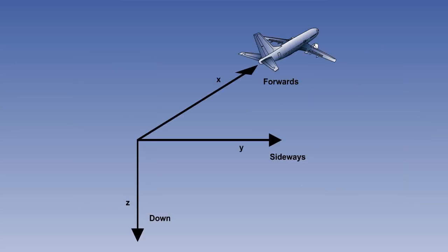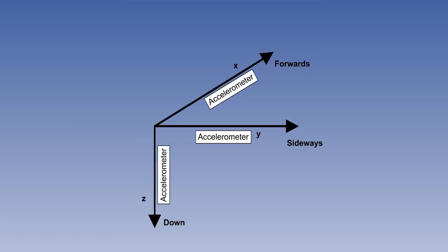The laser gyro can measure our aircraft's changes of orientation very accurately, but we still need a reference datum for our basic directions: longitudinal, lateral, and normal. We do not have a stable platform with IRS. Our accelerometers are pointing in the direction of the airframe. However, for our velocities to be useful to us, we need them in terms of north, east, and vertical.